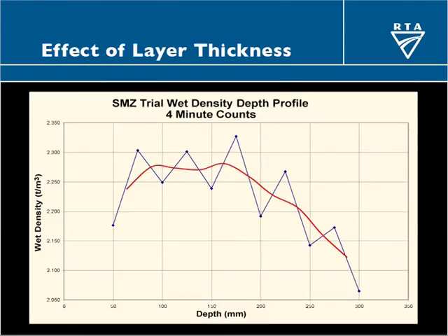And what we have found can be illustrated on this graph. The densities were determined by difference using a nuclear meter at 25mm intervals, then averaged through the lot. The zigzag line that you can see on this graph represents the averages for each lift. And as you can see, it's a bit of a sawtooth, but appears to be going down to the right-hand end, which is greater depth.